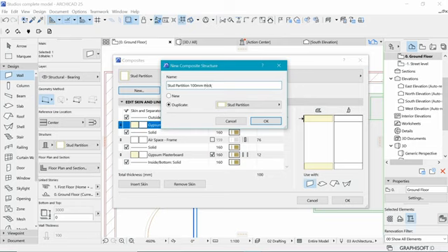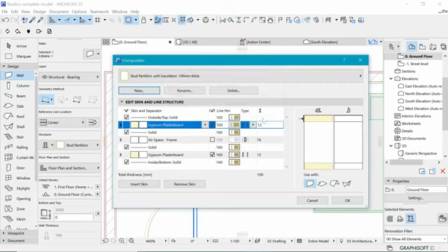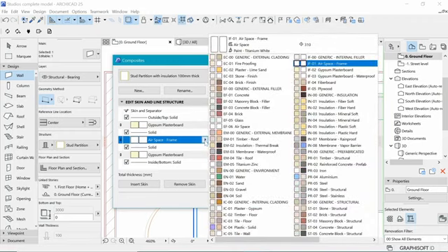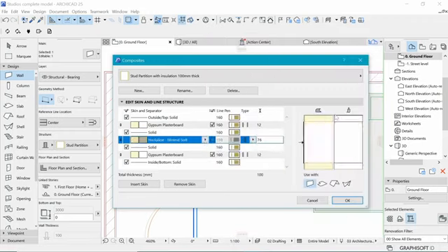Ours is going to be stud partition with insulation. Let's just add some layer of insulation, like foam board or something like that. Okay, so we have created our own, and then we go in here and we will have a gypsum plasterboard at the beginning and then a gypsum plasterboard, and instead of just having space, we will fill it in there with some insulation, mineral soft, something like styrofoam in there, so we can have some timber frames in that position for stability.